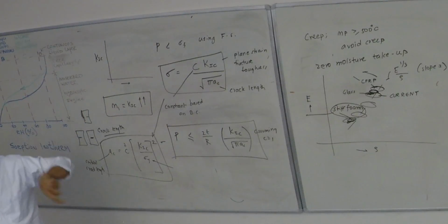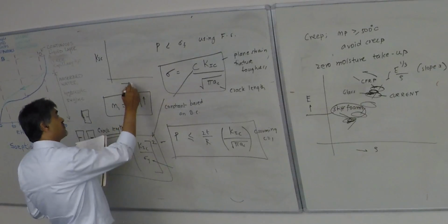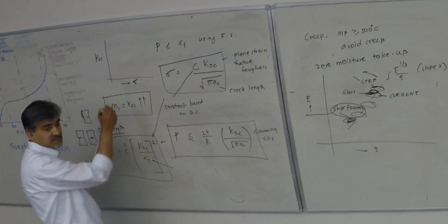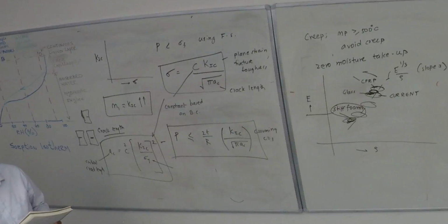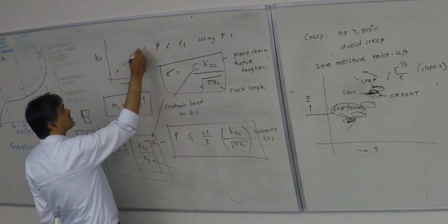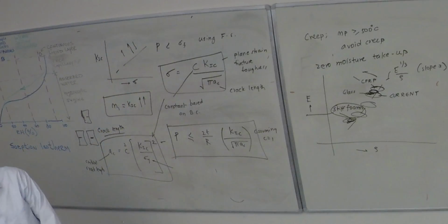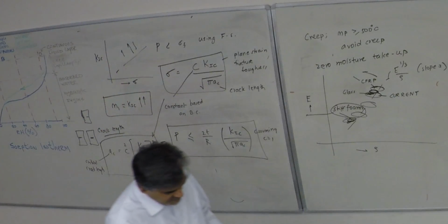And then apply that to check if a certain crack length is met or not. So you're looking for the largest value. Maybe you can plot sigma versus K1C, and then look at this index, maximizing the index on this side, to see which materials would satisfy that application.